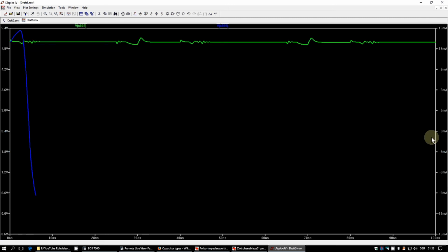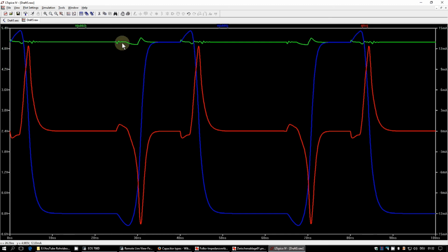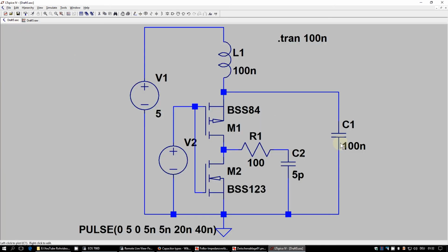And you can see that it's much better. On the supply voltage, there's nearly no drop or no ringing. It's so low that it will be even difficult to see on your scope. And here the waveform itself is nearly unaltered due to this very small ringing. So it's nearly perfect. And so there you could see the reason why modern MLCC capacitors are a factor of 10 better than using plastic film capacitors as bypass capacitors.